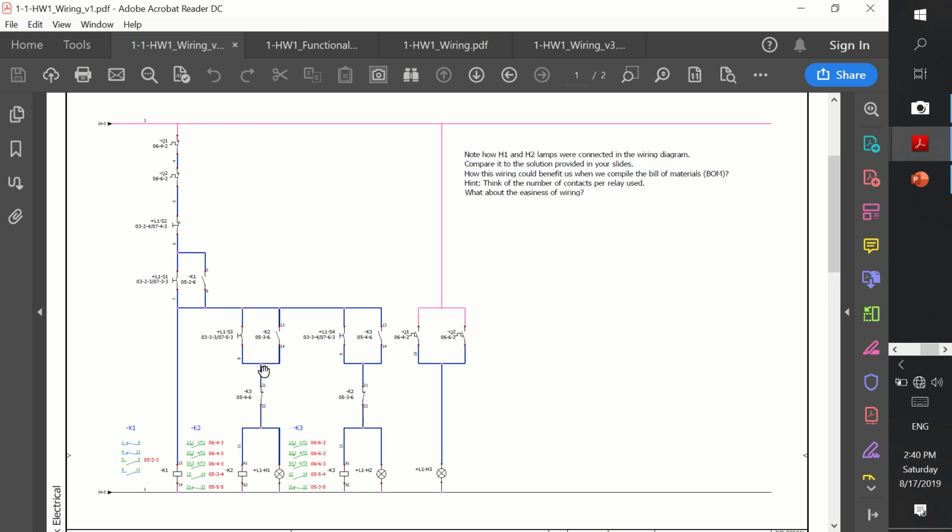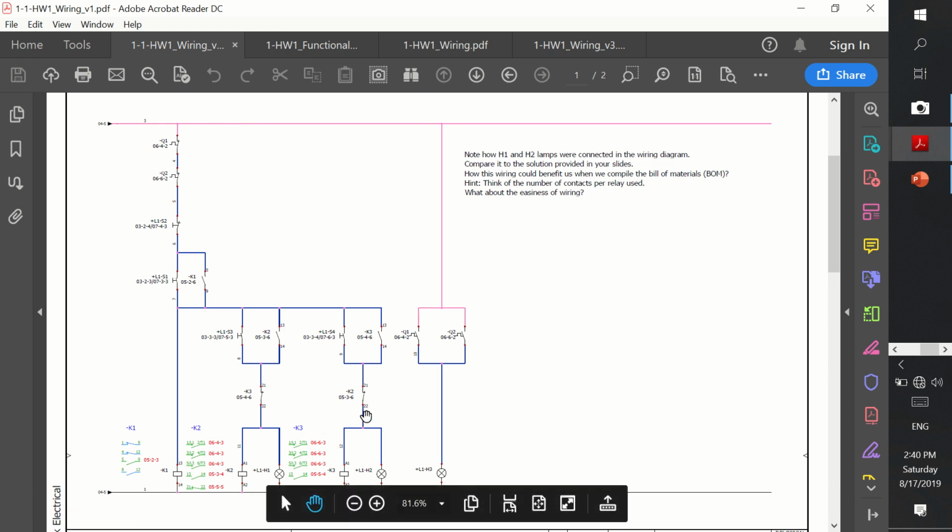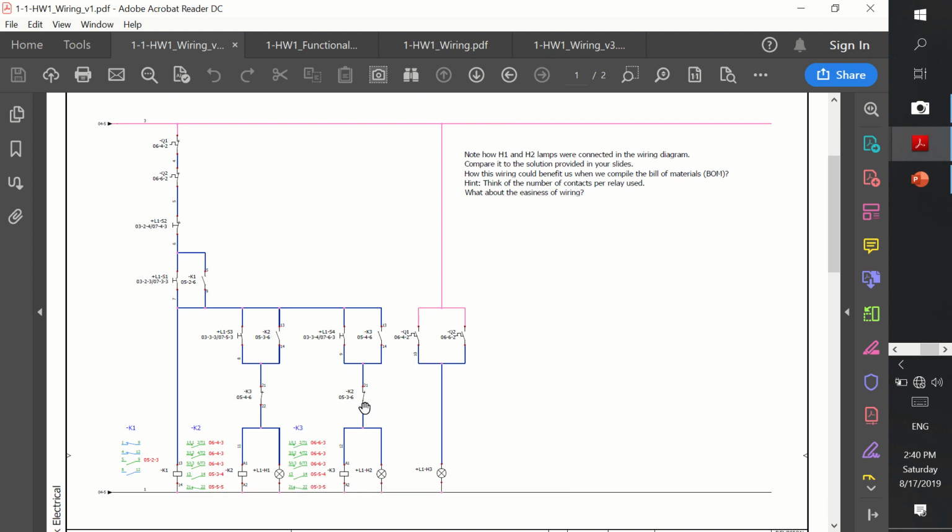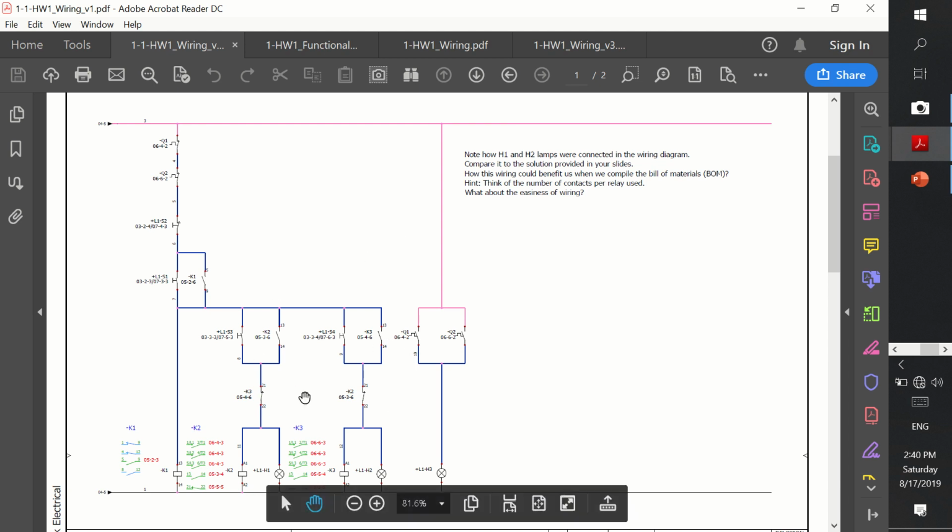In fact, the main issue I was facing earlier, that I have 2 power contactors that are operated using 24 volt DC, but I was lacking the overloads. So I have to reconsider this. And another issue where I was faced with the lacking of sufficient number of normally open, normally closed contacts, where I have in fact relays with 2 switchover contacts. So I was unable to realize the circuitry shown here.